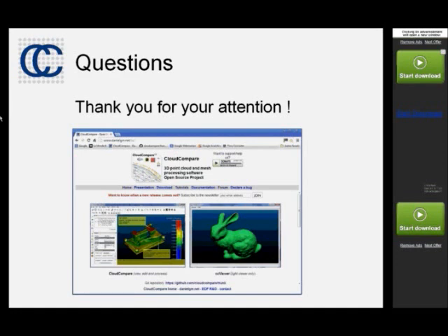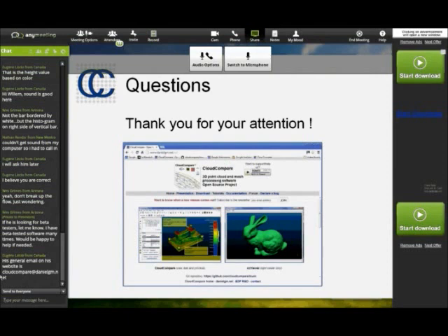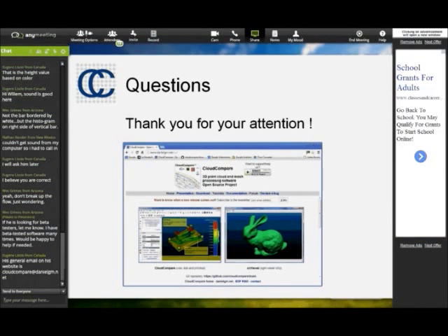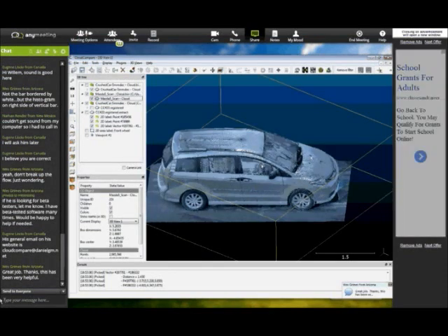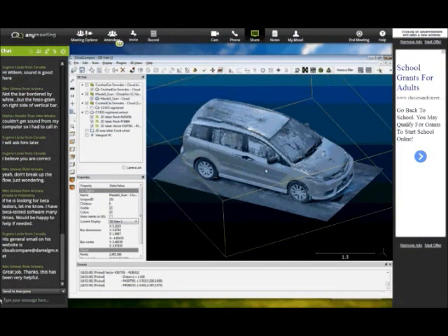Daniel, I have one thing before, and I think it's a very useful tool. In the subsampling, could you quickly show how you can subsample one of the cars, maybe with a space limit? Because for a lot of people, when you scan, the points closer to the scanner can be very, very dense, and maybe you don't need that kind of density. I found this to be a very useful tool for lightening the point count, but still keeping the density where you need it.